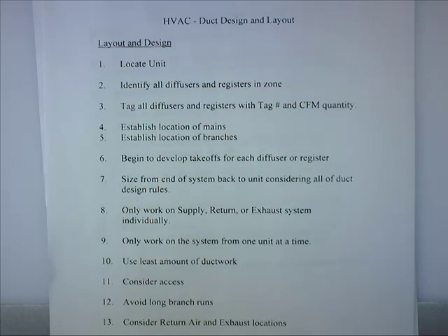We're only going to work on one system at a time. We're not going to do separate systems. We're going to work on the supply, and then the return, and then the exhaust. You want to try to come up with a system that uses the least amount of ductwork, because ductwork costs money.